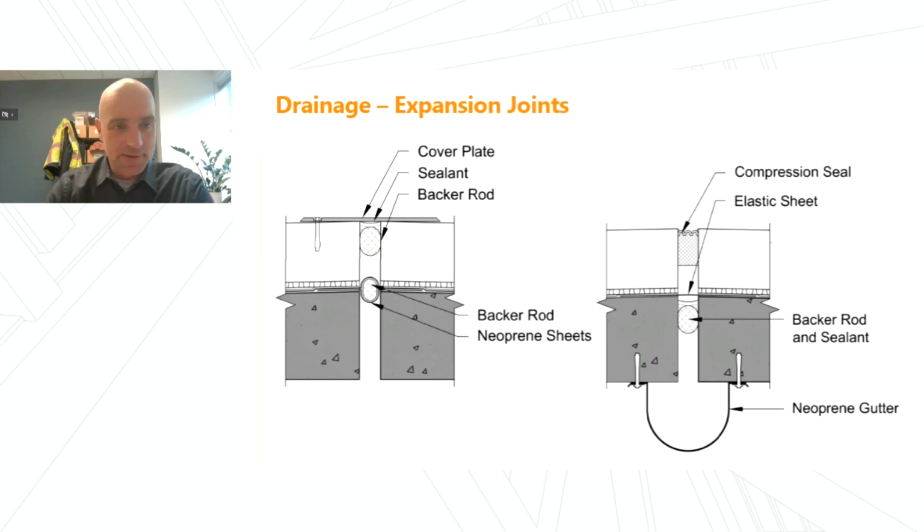And then expansion joints. There's a lot I could say here, but in the interest of time, I will tell you this. Paul and I have lots of conversations about redundancy of expansion joints and secondary seals. And I think it's always a trade-off between performance, durability, and access and ability to repair these in service. The diagram on the right is from an expansion joint that we had to troubleshoot and figure out the cause of a water leak. And you can see there's multiple water seals.